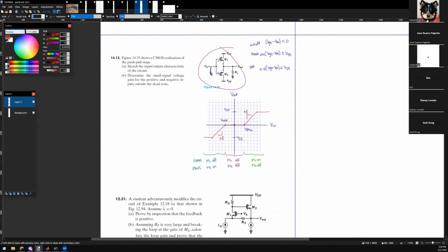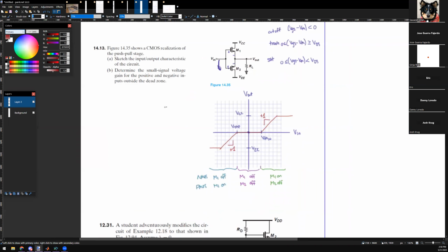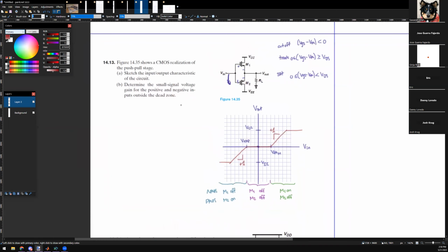So this is a very efficient amp. You're trying to build a very efficient amplifier. Anyway, that's some context. But there are multiple reasons why you want this type of push-pull configuration. It's called push-pull because each FET has its own role: this guy pushes current in, and this guy pulls current out. That's kind of the idea.